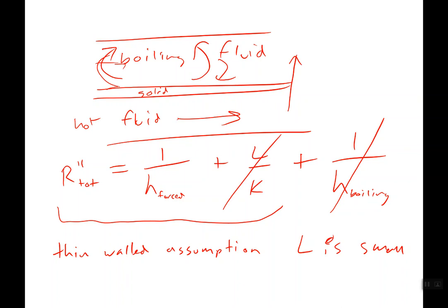So when you get boiling, one of the assumptions you can make is that there's no thermal resistance because that boiling just takes the heat and immediately sweeps it away. So the thermal resistance tends to go to 0. In certain cases, if you found that this h was significantly higher than this h, then this h would become the limiting factor, and that would basically be the main component of our overall heat transfer coefficient.